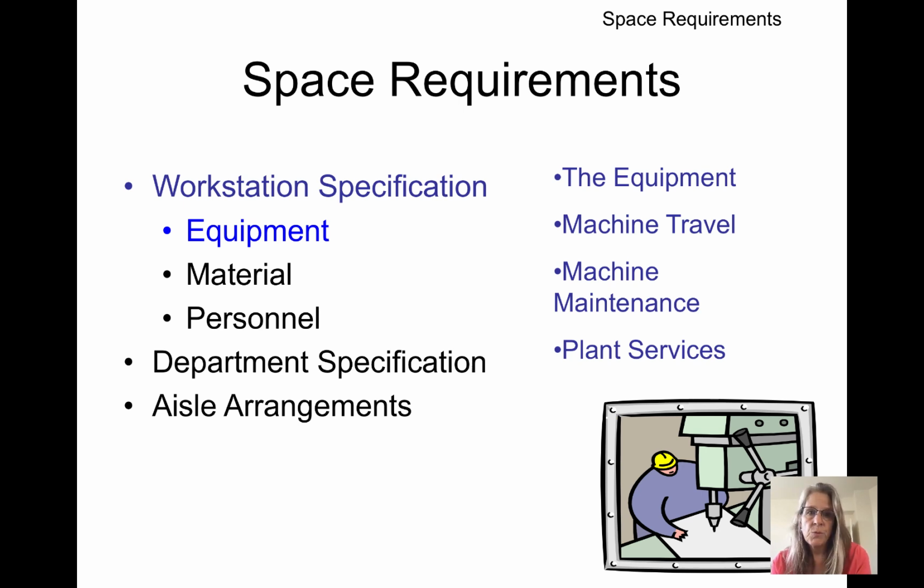For instance, if it's a robot, the particular footprint is quite small, but it might actually be moving around quite a bit, and you want to consider that total travel area as the footprint necessary for the equipment. You also want to consider tables and desks and tool chests, so anything else that might be needed in order to work in this particular area.